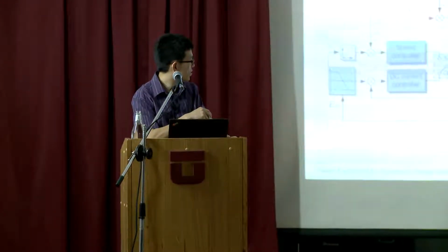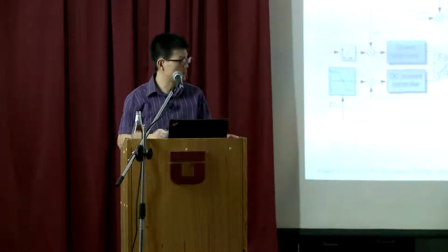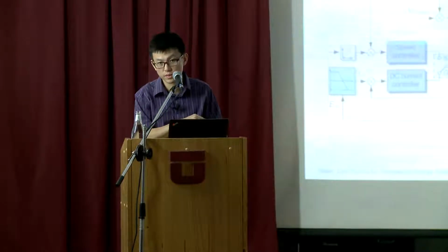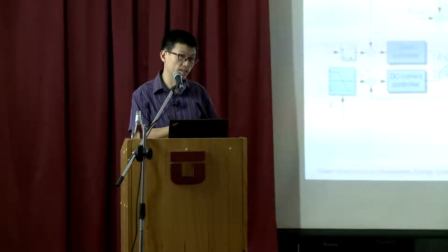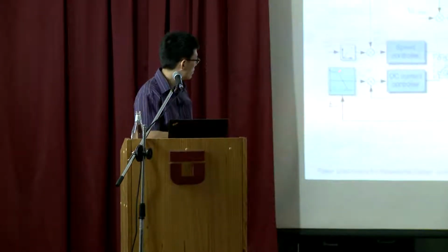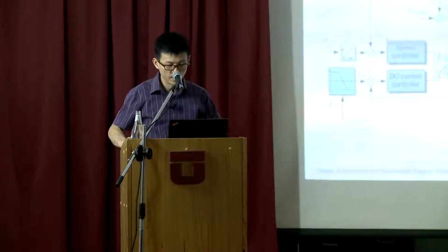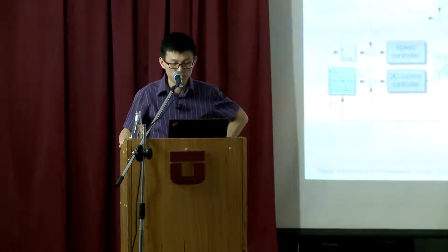These two currents we call the DQ axis. They change from the ABC frame to the DQ frame. ID and IQ are constant values, not sinusoidal, exactly like the DC motor. And the droop control is here, so we do have the droop control for this generation system.